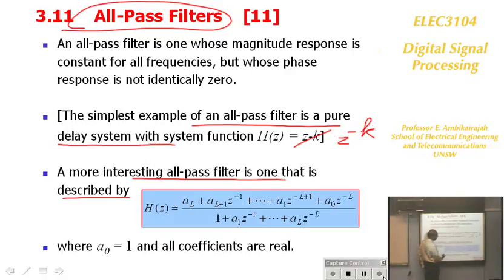You will find, when you look at an all-pass filter, that this coefficient is equal to the last coefficient there. And similarly, you will find that this coefficient is equal to that, and also that one. This A naught should be here. They should be the same. This should be A naught really. We don't normally have A naught here, right?